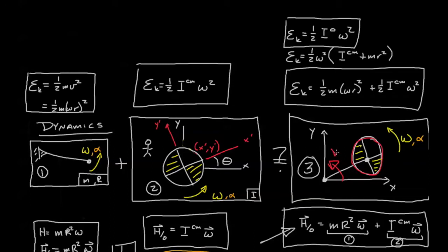So one can imagine if you applied some work in scenario 3 and the same amount of work in scenario 1, scenario 3 will have a much lower angular velocity because the work is building not only this aspect of kinetic energy, but also this aspect of kinetic energy. Whereas in scenario 1, you have the work only building one term, which means that omega is going to get a lot higher. So hopefully this brief intuitive look at kinetic energy and work in a rigid body rotating about a pivot gives you a more fundamental understanding of what's really going on there.